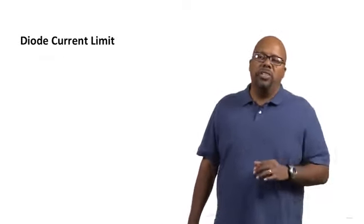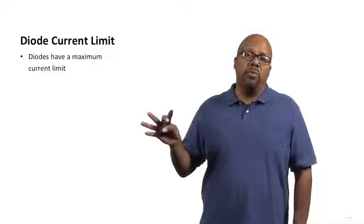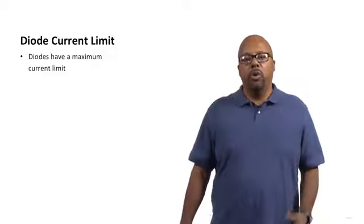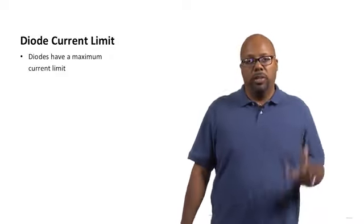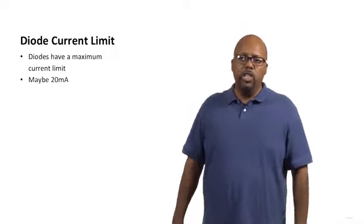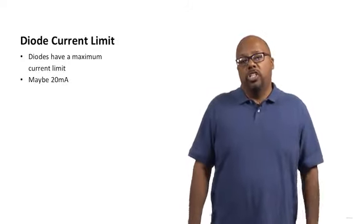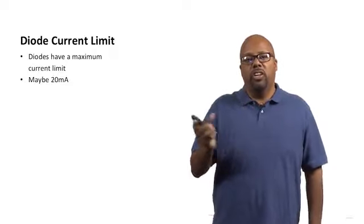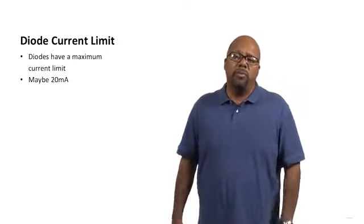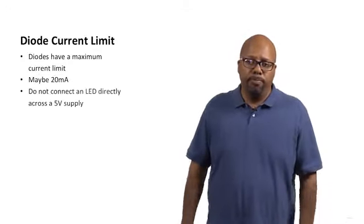Another property of diodes is that they have a current limit. They have some maximum current, and you should not drive them with more than that current. You can probably push it a little bit, but it will wear down more quickly. And if you drive too much current, it'll just blow up and it'll never work again. When I say blow up, it might pop, and you just will never see it working again. For typical LEDs that I use, 20 milliamps is the current limit. This is also the limit for the LEDs in your kit, if you got the kit. If you push more than 20 milliamps through it, it will die pretty quickly.